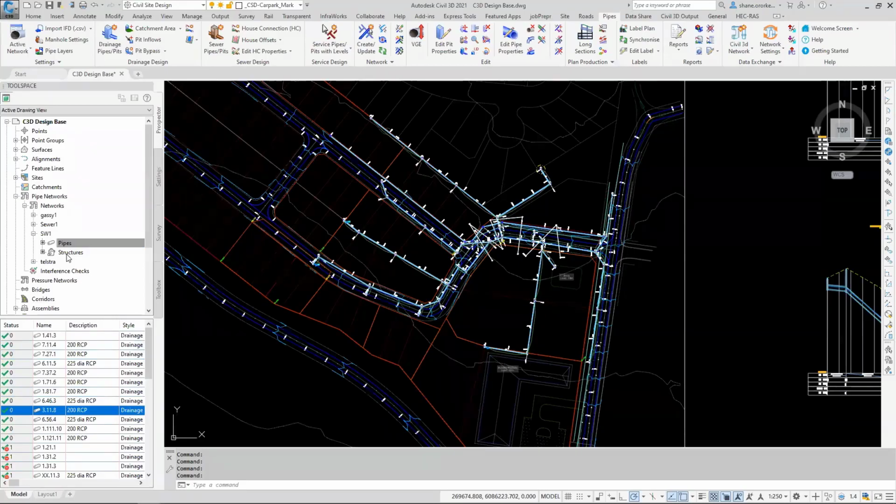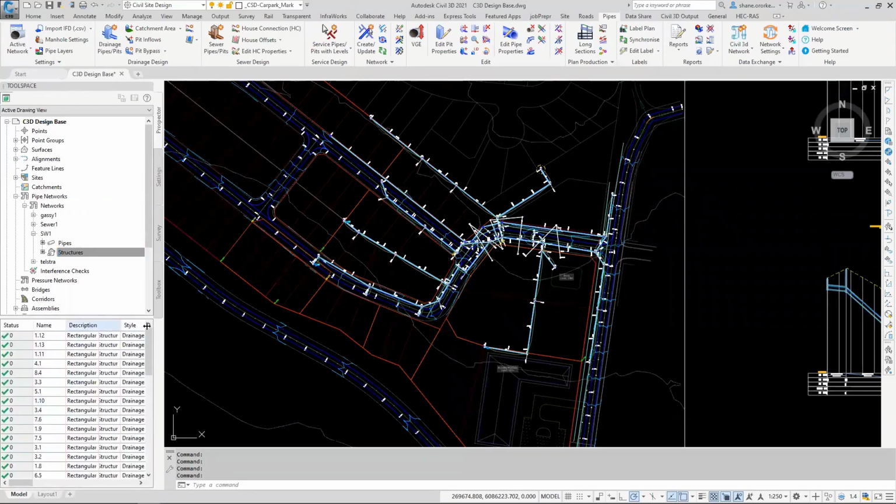If you compare that to the structures where I didn't tell it to overwrite, lots of people have said across the forums that they wish they had control over this, because this otherwise comes from the catalogue. So if you don't like the automatic descriptions that get assigned to the different structure types, the exchange settings will let you preset and manage that.